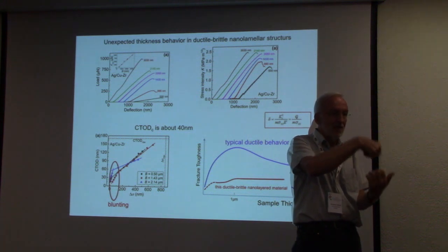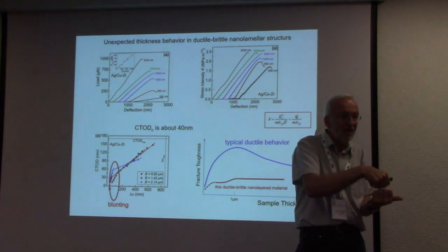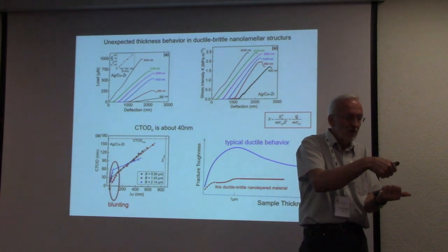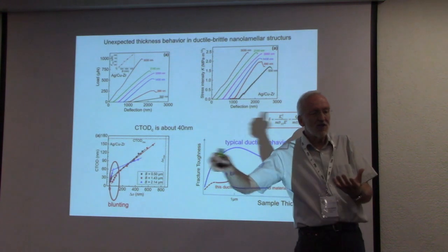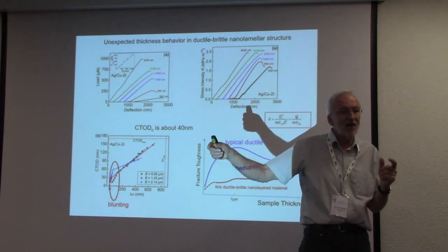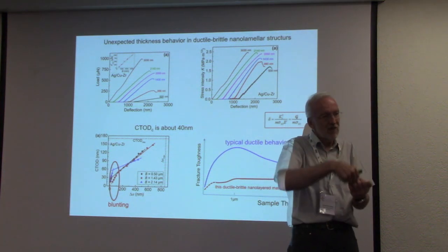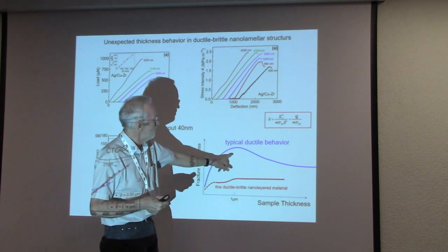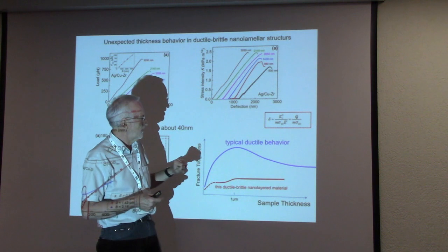And we have seen that in plane stress, the stress in loading direction is significantly smaller than in plane strain, and therefore the formation of pores is shifted to significantly larger strains. We can load up the sample to significantly larger strains. Only in the interior of the sample where plane strain takes place, we have some crack propagation.